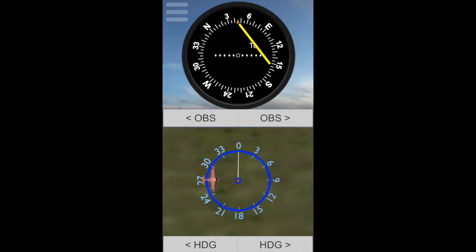270 radial, 270 inbound. Why? Again, these are radials, not directions, in the sense that we're not telling you to go towards heading 270. We say 270 radial, 270 inbound. This is a radial. Any radial is a line with an arrow sticking out of the VOR station itself. The 270 radial is that line coming out of the VOR station going west. Then you track it 270 radial inbound, which means towards the VOR station. So that means you're going to fly this way.